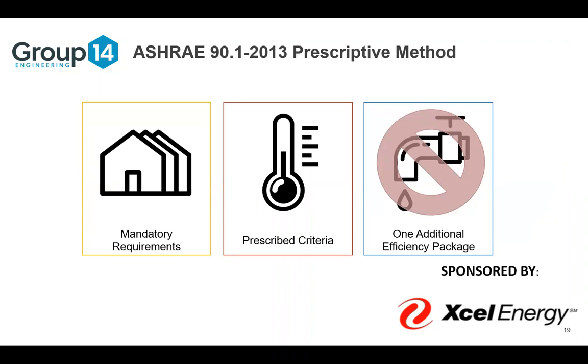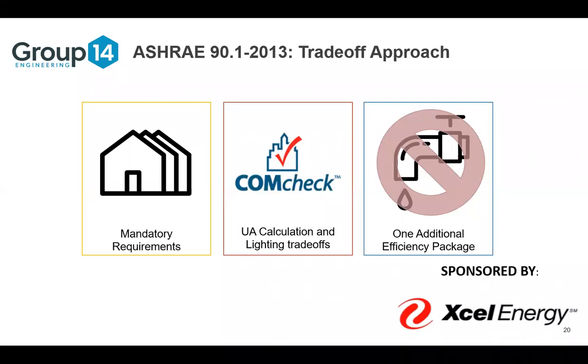Now we're going to compare to ASHRAE 90.1 2013. They have mandatory requirements and prescribed criteria, and they do not have additional energy efficiency packages. We have seen quite a few multifamily projects start looking at complying with ASHRAE 90.1 2013 via their energy performance method, which I'll get into in a minute. There are mandatory requirements, and they can still do the UA calculation and lighting trade-offs just like you can in IECC.